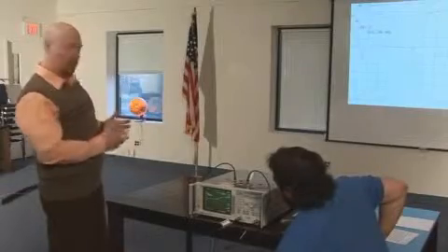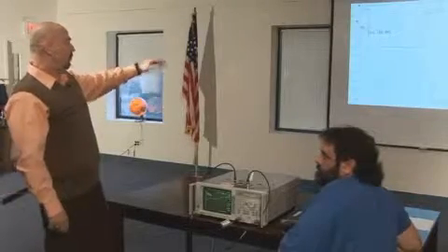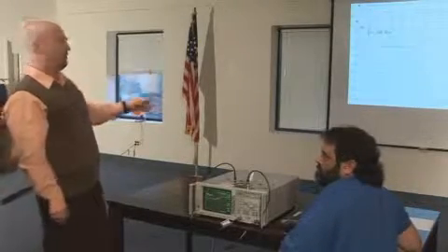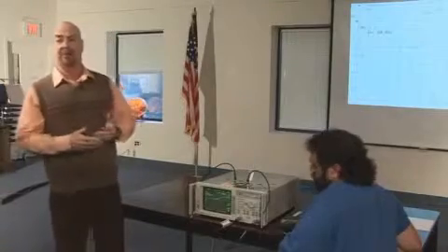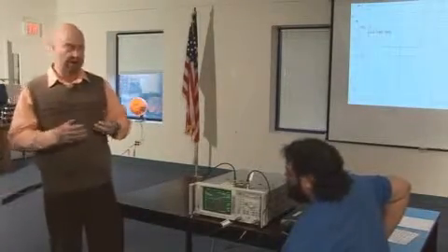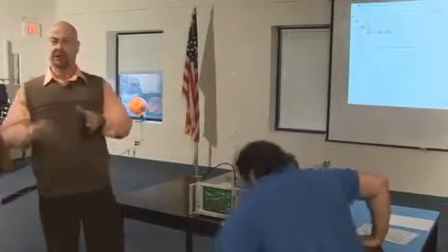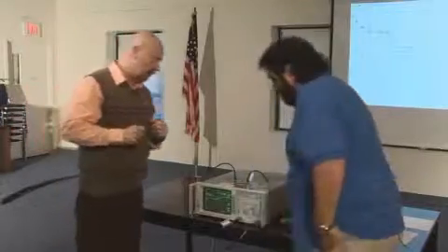So if I only need about 20 dB of rejection, I can put this in, and if my signal strays anywhere from 30 to 400, I will get some amount of attenuation on that signal. Then I don't have to be worried much about whether the peak of my notch falls at one point or another, because I have a wider area that I can look at.